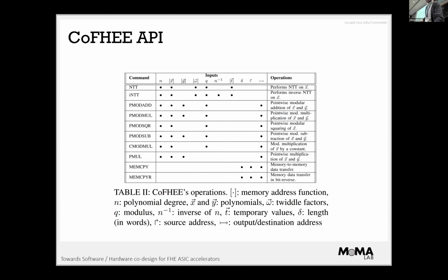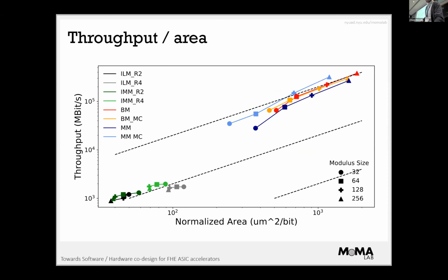The ISQED paper has the same exploration with pipeline stages too. So you see for different pipeline stages how the multipliers respond. However, pipelining is not an idea that can be employed easily past the functional units. The rest of the chip is memory that moves around. So in that context, pipeline is meaningful as long as you can feed it, and your initiation interval starts playing a big role. How fast can you bring things to the functional units?